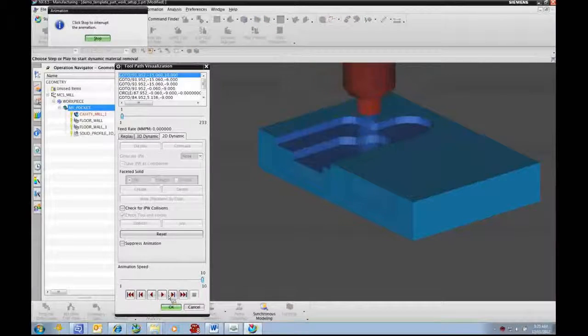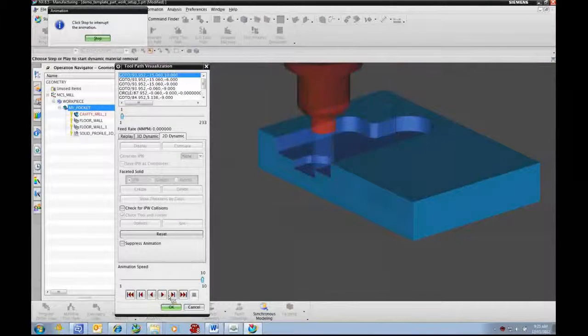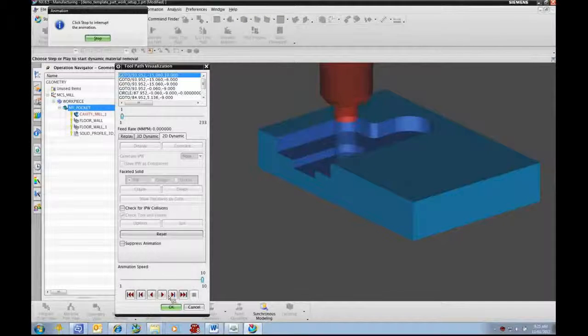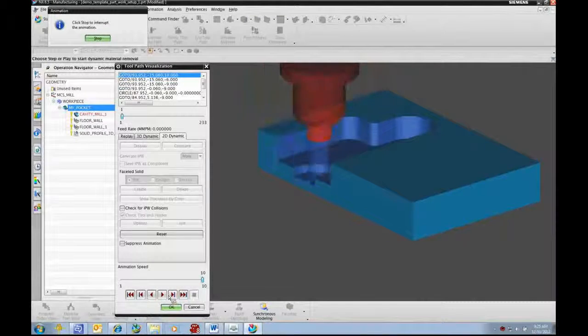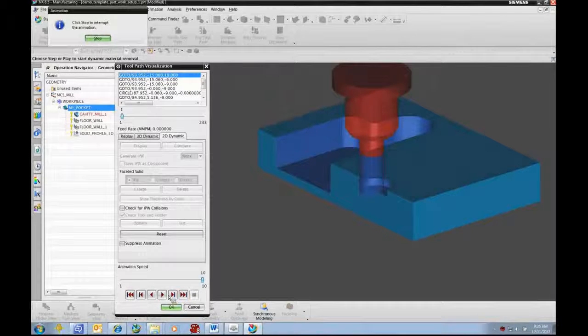And again, whatever you find works for your shop, this is the idea. We don't want to have to go in here and create cavity mill, change the step over, change the cut pattern, change the depth of cut, select the tool, if we know what works. So my assumption is that in your shop, somebody knows what works, right? We can't dictate a process for you, but if you have a process that works, what I can help you do is reuse it so that everybody uses the same process over and over.